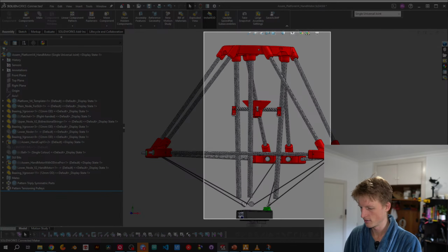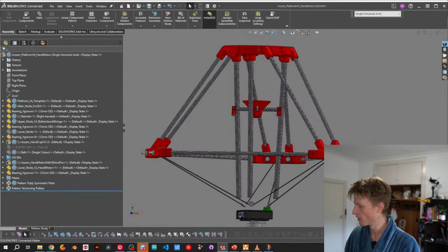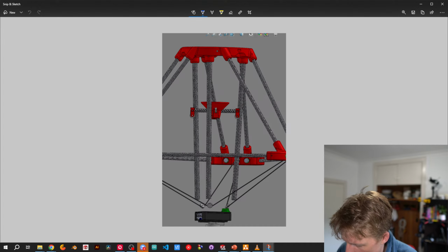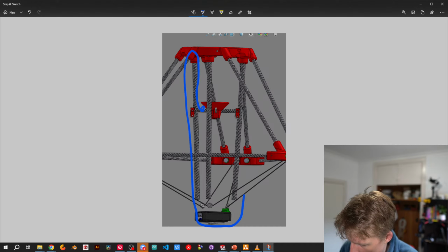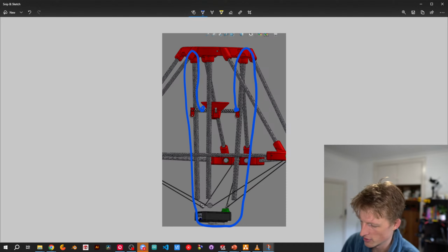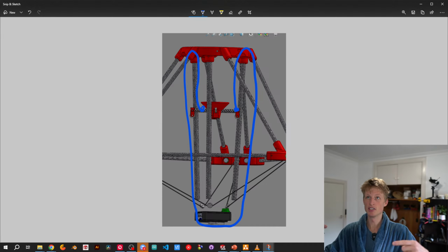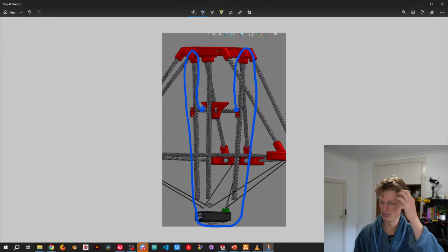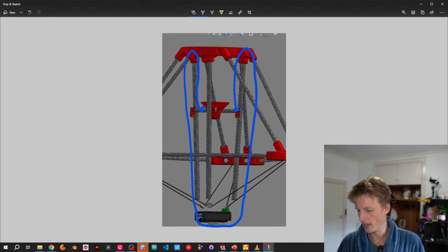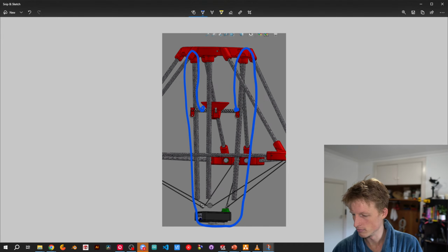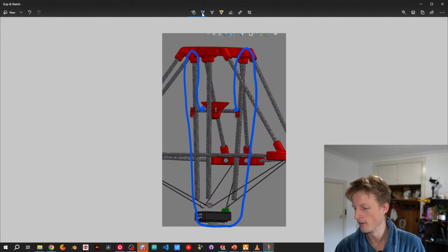Let's do it like this. Okay, yeah, so the string attaches to the hand somewhere, goes up over the pulley, down through the spool, up, down, onto the other side. At least one of these ends will have a little length adjuster thing, it's the same as what I've had before. And then the other side, so this will be to pull the hand up.